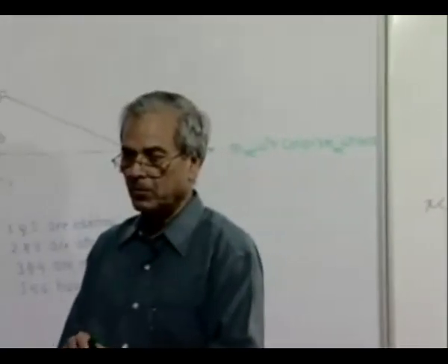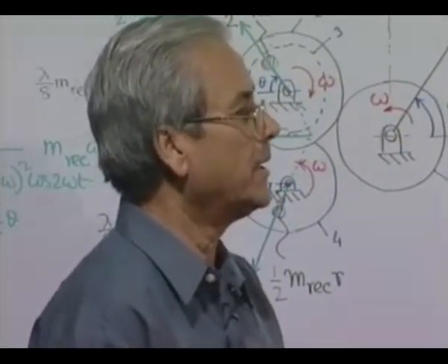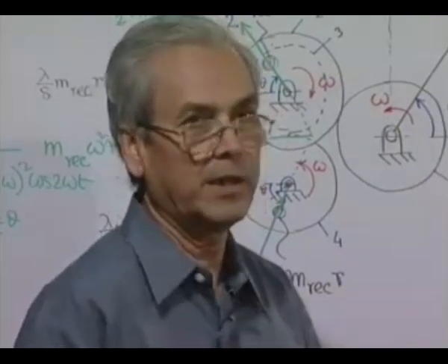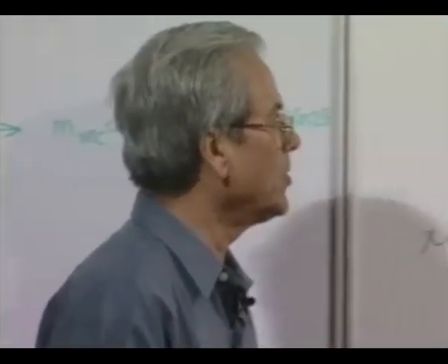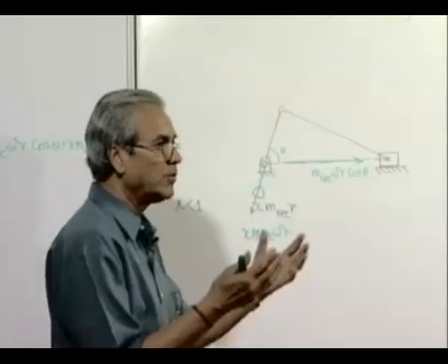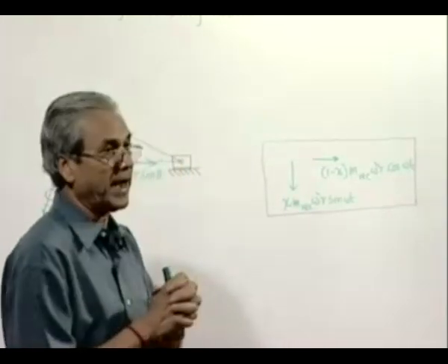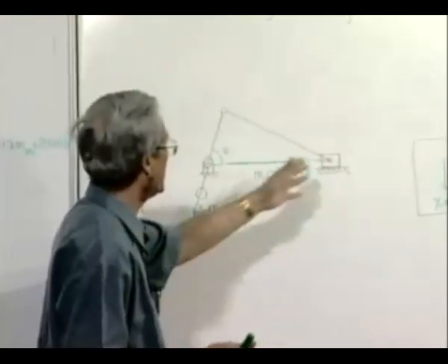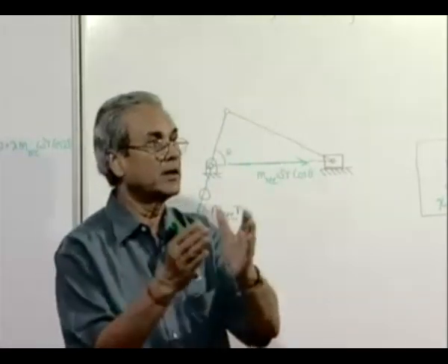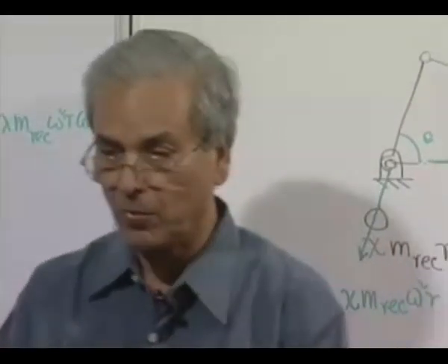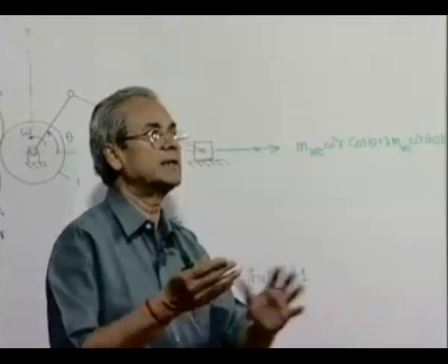Now, situation is much better, as we know, when a machine is designed keeping its smooth functioning in mind in such a way that we do not use a single slider system. If we use multiple slider systems, then you can really appreciate the fact that it will be possible for the unbalanced forces generated by the reciprocating masses in the various components of that machine, that means each one composing one single slider system, they can neutralize among themselves.